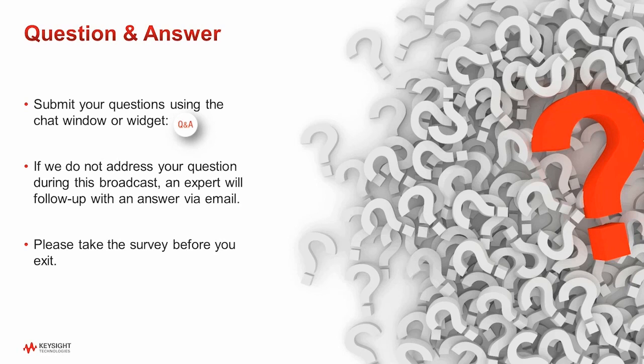Yeah, so that's a great question. And I think the answer depends on the application type and needs. Taking reference from the ORAN Fronthaul architecture, it recommends not to use Jumbo frames where there is a need for bounded latency for time-critical traffic, mainly eCPRI IQ data. The reason is that use of Jumbo frames is normally avoided as they can impact the overall latency of the network.